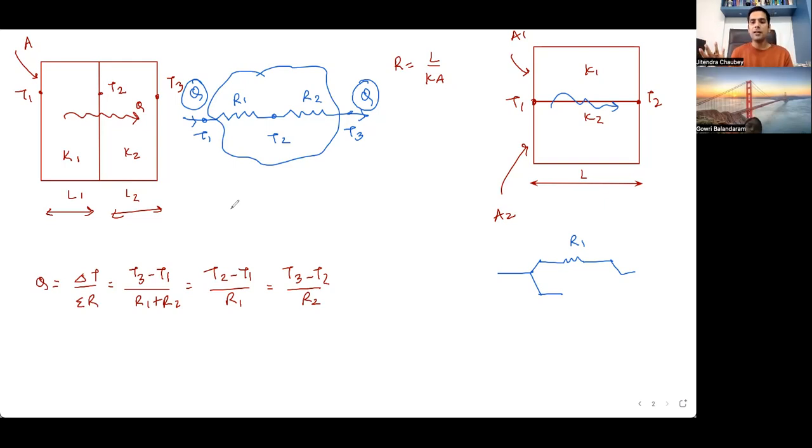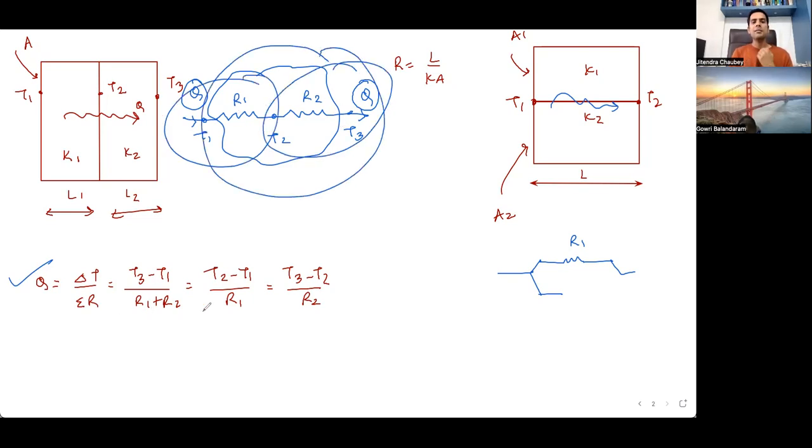Not that any object in the planet can absorb heat continuously throughout its life. There will be a point wherein it will get saturated. It is after the saturation that we study and solve the numerical. That is where the steady state is reached. So heat is entering and heat is leaving, and the quantity remains same. That's why the formula comes that delta T for this, delta T for this, or overall delta T can be simply written in the form of same Q.